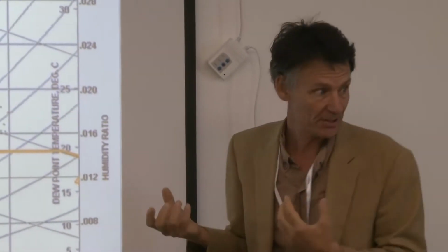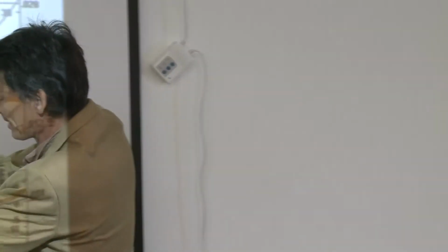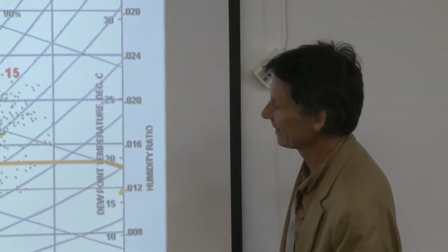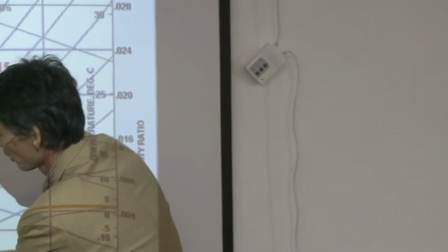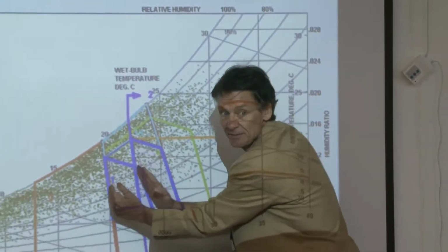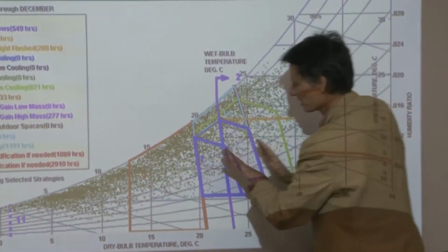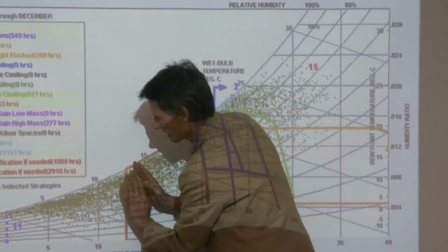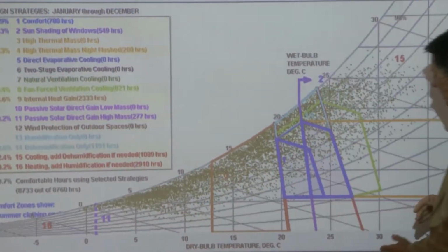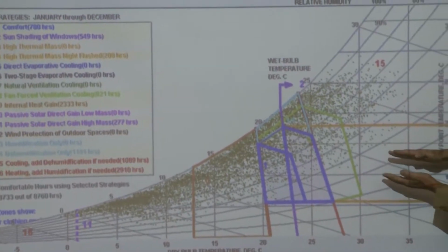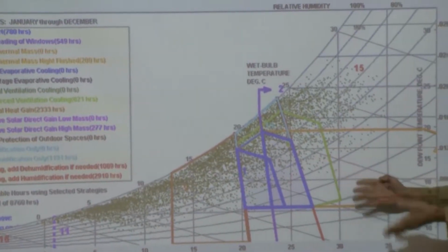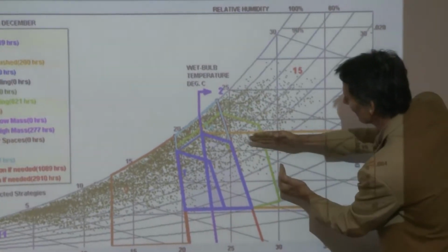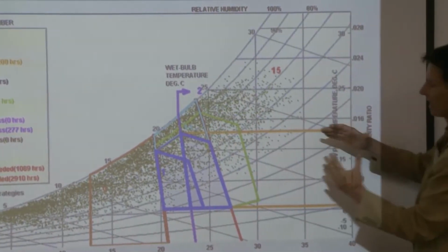And that's really neat, but there's that problem of there aren't EnergyPlus weather files for everywhere in the world. And so this is what I'm going to talk about: how do we pick up this beautiful chart? I found it really fascinating. How you can look at where is your comfort zone, and this is where you're adapting. You know, winter and summer, we have different expectations of how we dress. But as you go into these points here, you can do passive low energy design, you can push the limits here, but then you're going to need heating systems coming this way. You come this way, there's limits to how far you can go with ventilation, either natural convection or forced convection. There's not really a lot of difference as long as you design it to work.